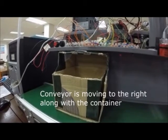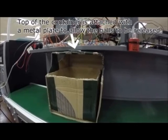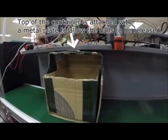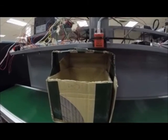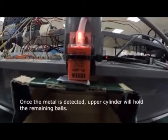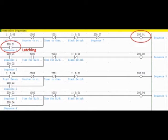The conveyor belt will move from left to right. The left sensor will first be activated by the metal piece on top of the container. When the left sensor senses the metal piece, the circuit for sequence 1 is completed and sequence 1 will be activated. Latching will also be completed at the same time the metal piece is detected by the sensor.